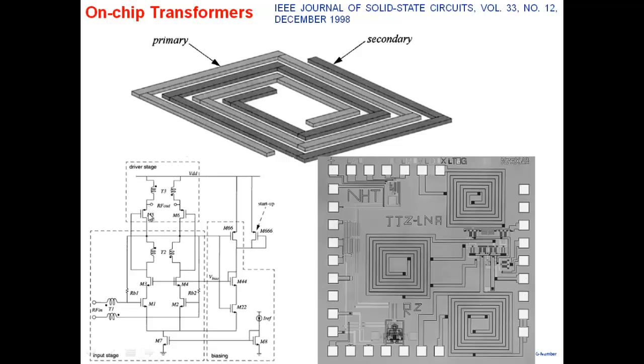And as I said, as you go to higher frequencies, the inductive effects become stronger. Inductive effect depends on omega and L. So inductive effects become stronger. And if you can minimize the parasitics, then you can get reasonable values here.